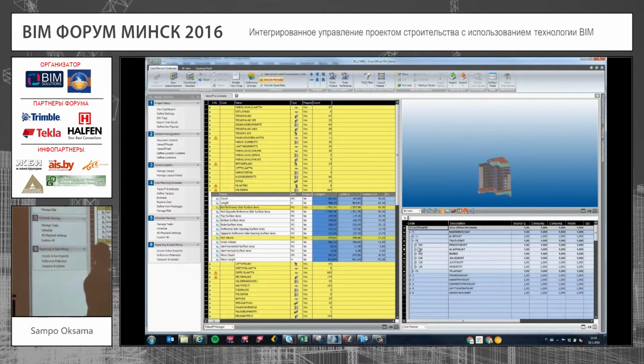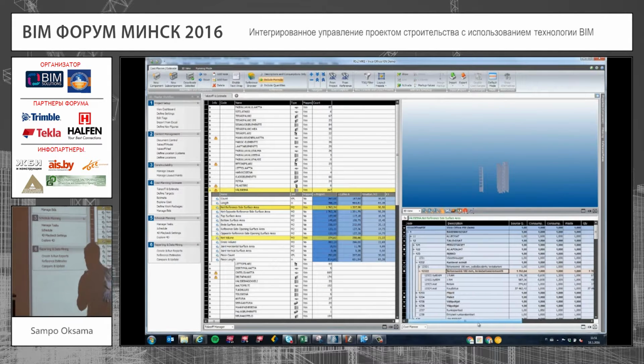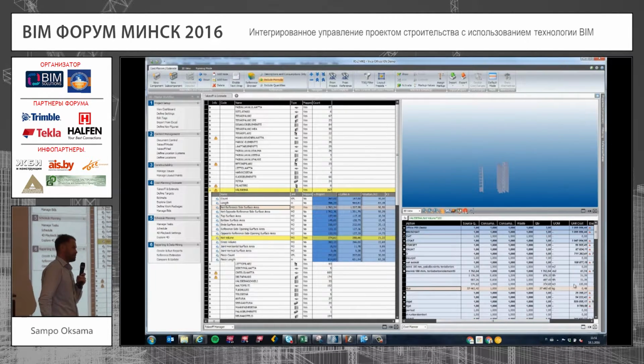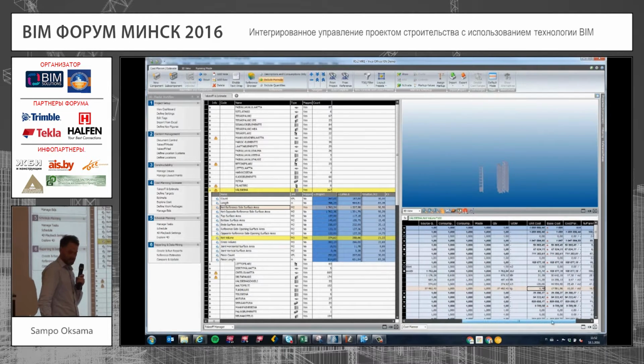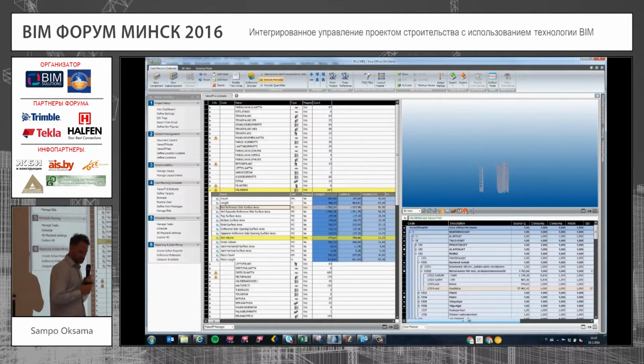Then here we have our company cost database, their market prices, and we just select from the quantity and say, for example for the inner walls, okay, let's calculate the area this time. And we know the unit price for one square meter of that kind of inner bearing wall. And that's how we get the total cost for that structure.